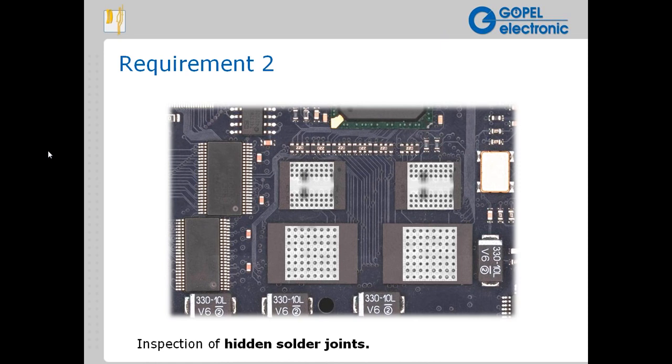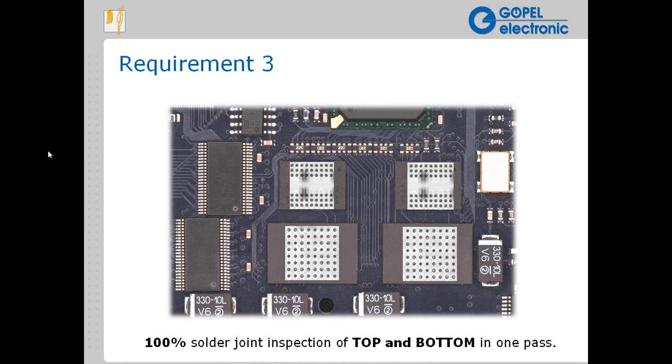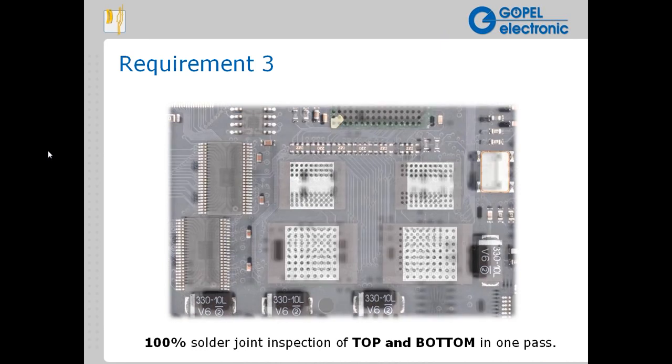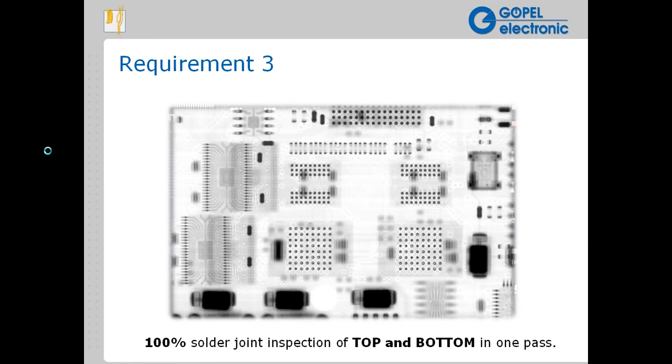There are cases where impeding devices or heat sinks or metallic structures, for example, may cause a problem with two-sided inspection. DFT, designed for test, is important in laying out boards to be most effectively inspected by 3D X-ray, so that certainly is a consideration. But as you can see here, when DFT is done properly and board layout is done such that it complements the 3D X-ray capability, very effective double-sided inspection can take place.